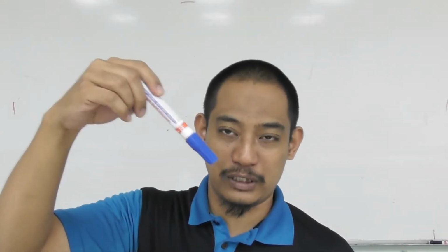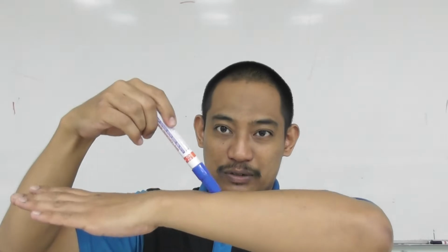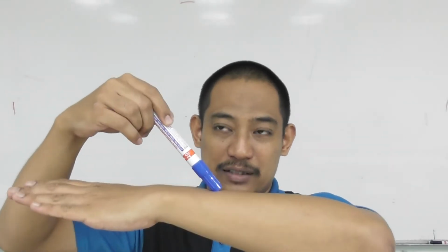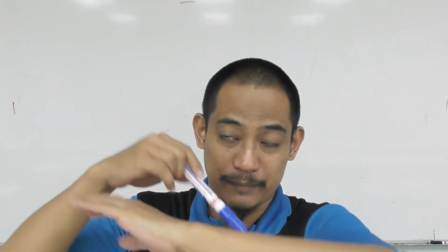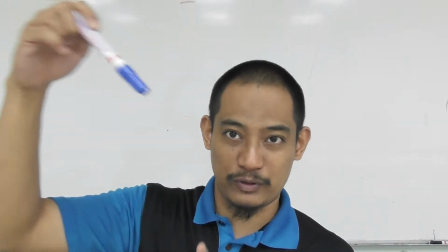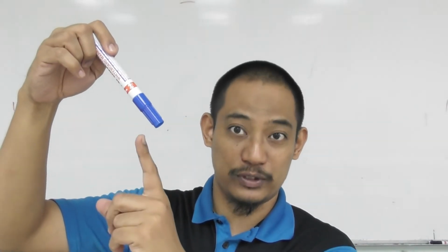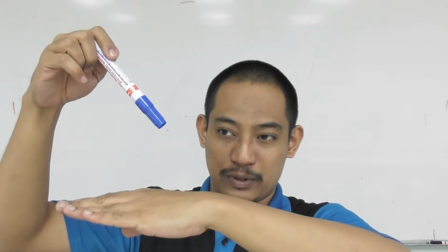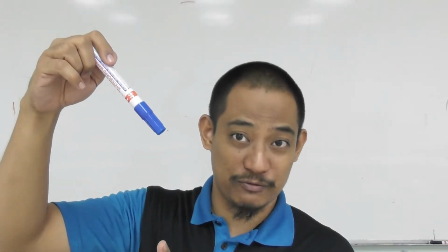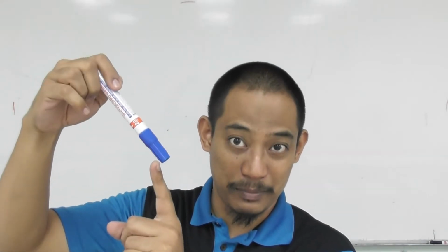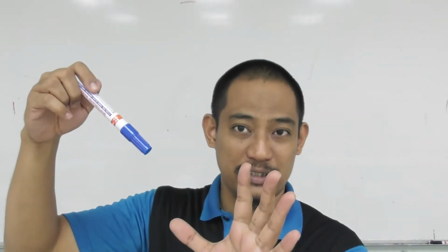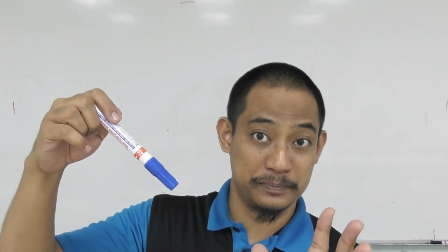If there's no ground there, it will just go down, but this one prevents it from going down, hence it stays there, it is static, right? So in that case, the free body diagram, when we draw, we just draw the force upward. Why? The ground is the one that is providing the supporting force so that it maintains in place, right? You do not draw anything else because there's no other restriction, right?